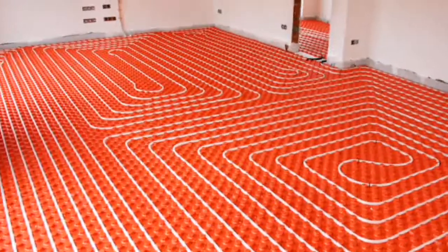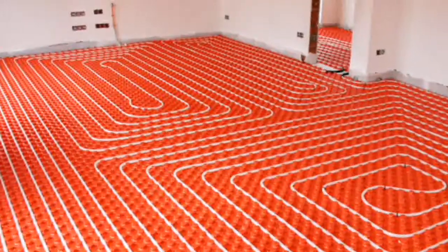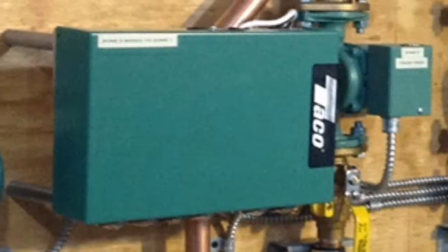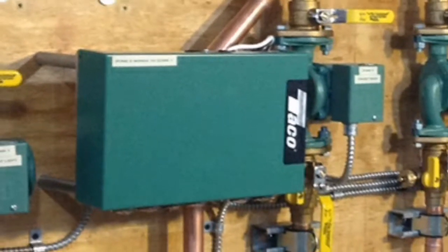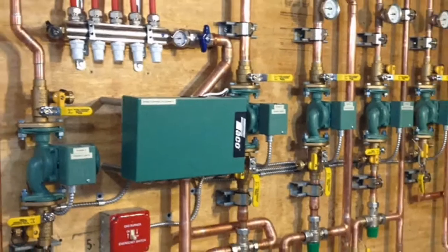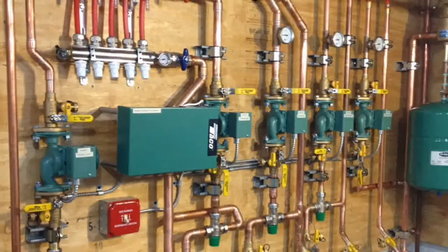Radiant floor heating systems are always zoned to allow for individualized control. The zone control panel is essentially the same as with convective heating, except that a solenoid valve or pump is being controlled instead of air dampers. Electric baseboards in every room inherently allow for individual temperature control. With radiant heat and electric baseboards, only heating is possible.